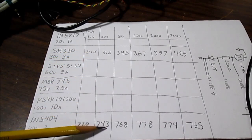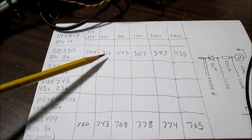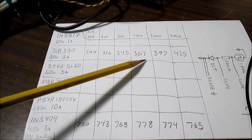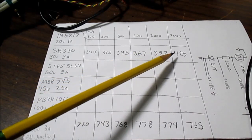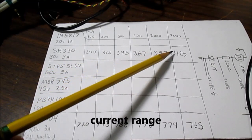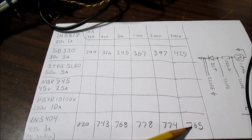Notice the much lower forward voltage drop. I did notice it was a lot more temperature sensitive, so I had to let it stabilize. As it heats up, the forward voltage did drop. You can see across the voltage range, it did change quite a bit. But at its maximum level, it's still quite a bit less than the silicon diode.